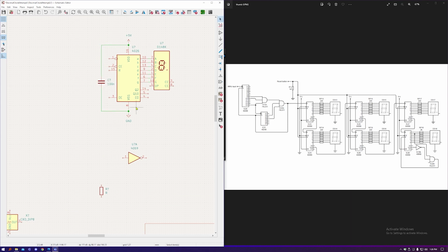Something I had pointed out to me recently, which is very helpful, is that when you're highlighting on KiCad, if you go from right to left, the only things that are selected are things that are entirely in the box you draw. Whereas if you go from left to right, it's anything that the box touches. So if you're trying to select a certain thing, just remember that. You can see with this capacitor, that's just the capacitor, but this gets the capacitor and the wires.